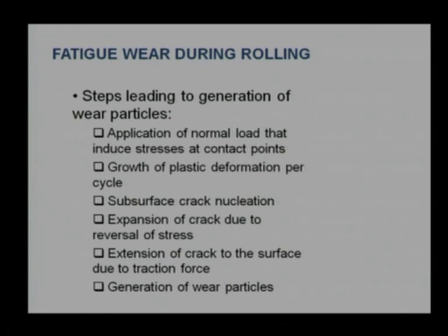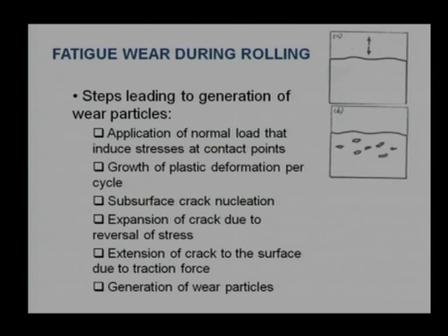I can show you all this, whatever we discussed on this slide, using some pictures. Let us check this in A: the surface is slightly irregular, and we are talking about the loading and unloading, the reverse of the loading. Loading is a compression; when the load is reversed it should come to 0, but there is a possibility of residual stress. We are loading something in compression and relieving it, quite possibly in lateral direction. We know that in the lateral direction there will be tensile stresses, and that tensile stress can generate some sort of nucleus or some sort of voids in a material.